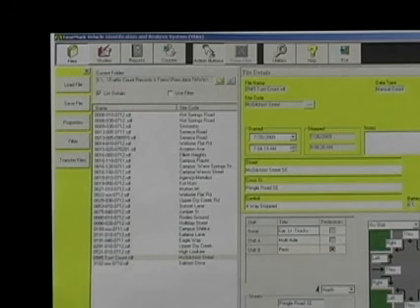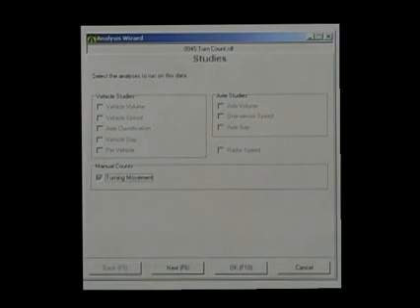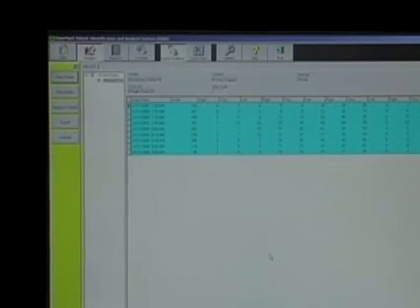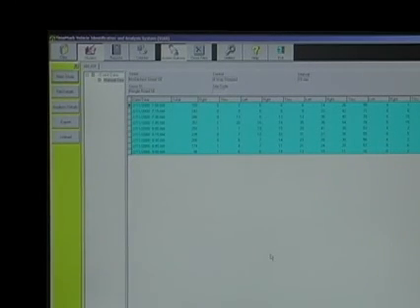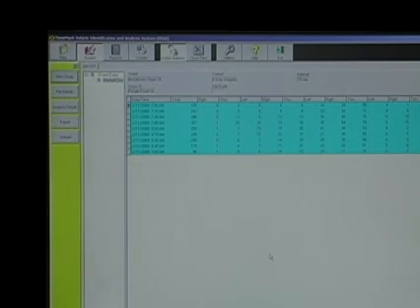To access the new file, you highlight it in the list of files and load the file. The analysis wizard opens again and you choose Turn Movement and hit OK. The file opens, displaying the time in 15-minute increments and the number of each type of movement through the intersection.